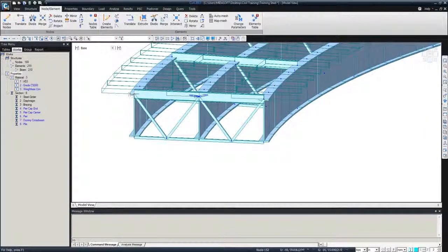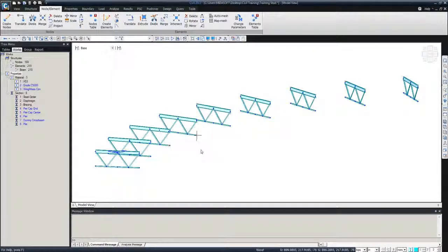But as I said, this node and this node are not directly connected. Look here, this is just one part of one girder. Definitely the top and bottom should work together because we assume that plane sections remain plane. This is why we have to connect these points. So I go back to the previous view that I had because it's easier to work here, and I want to connect these points to each other.